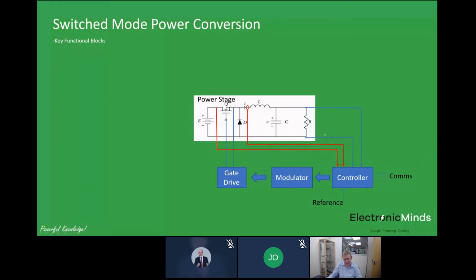And in peak current mode control, the controller also has knowledge of the current, the cycle-by-cycle current flowing in the primary magnetic storage element, or some representation of that, and that can offer some transient response improvements because you're essentially directly measuring the energy in your circuit. And we'll talk a little bit about those control algorithms in our later webinars.